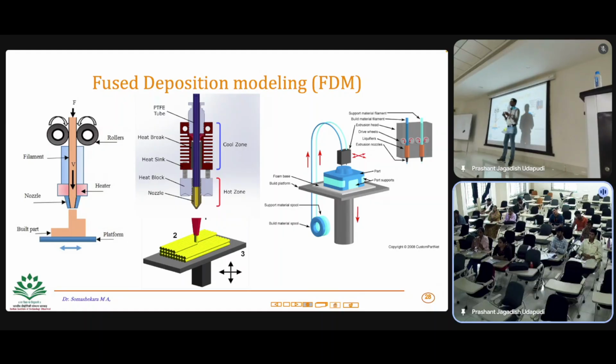Sometimes you want to print more material, to increase the printing speed, and there you need to go for a bigger nozzle. Sometimes you may be mixing in some powders, so there you may have to go for a slightly bigger nozzle, and make sure the powder does not settle at the nozzle, otherwise it will clog. Most of the issues with material extrusion are nozzle clogging.